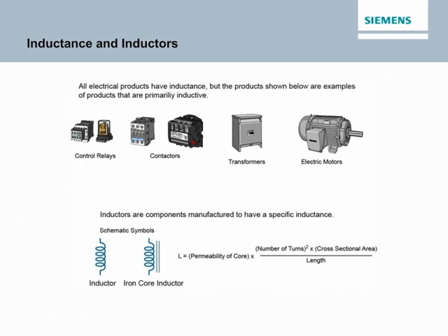Current flow produces a magnetic field in a conductor. Any change in current causes a corresponding change in the magnetic field surrounding the conductor that induces a voltage in the conductor while the change is occurring. This self-induced voltage, sometimes called counter EMF, opposes the change in current. In a DC circuit, current may vary somewhat, but most significant current variations occur when the power is turned off or on. In an AC circuit, the current is constantly varying.